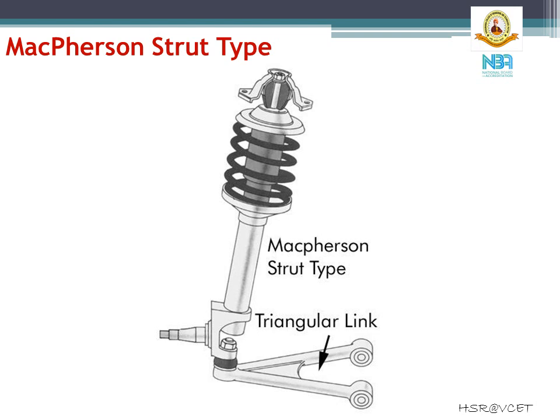The wishbone is hinged to the cross member and positions the wheel as well as resists accelerating, braking and side forces. The camber also does not change when the wheel moves up and down. This type of suspension gives the maximum room for engine compartment and is therefore commonly used on the front wheel drive cars.